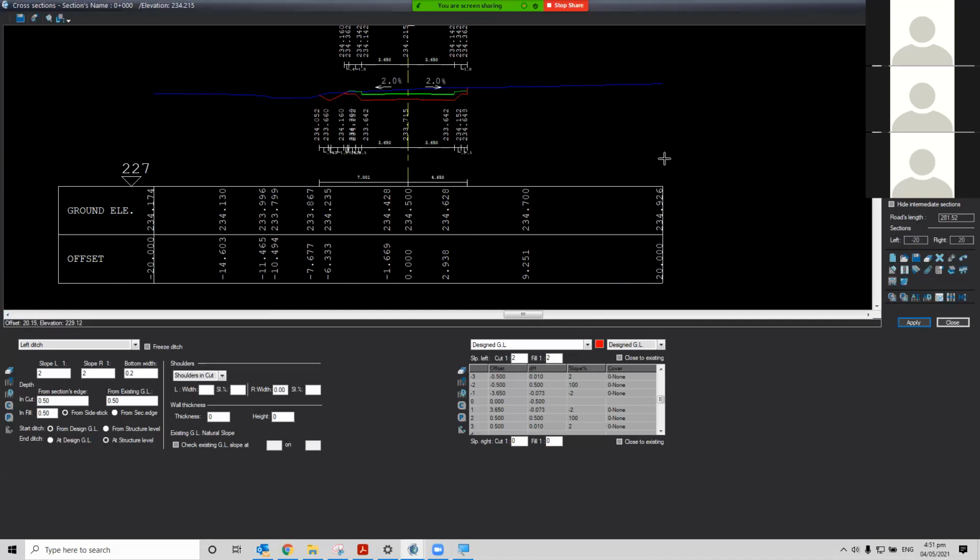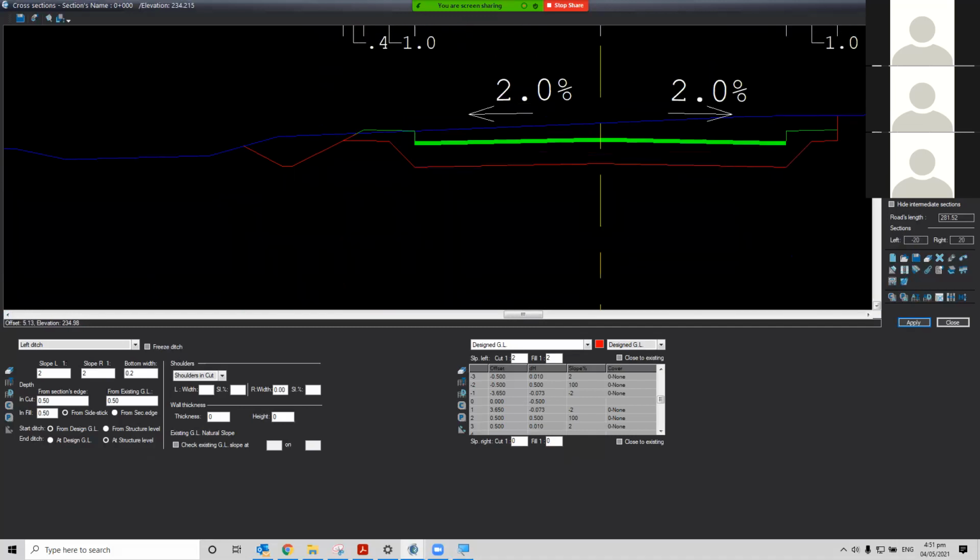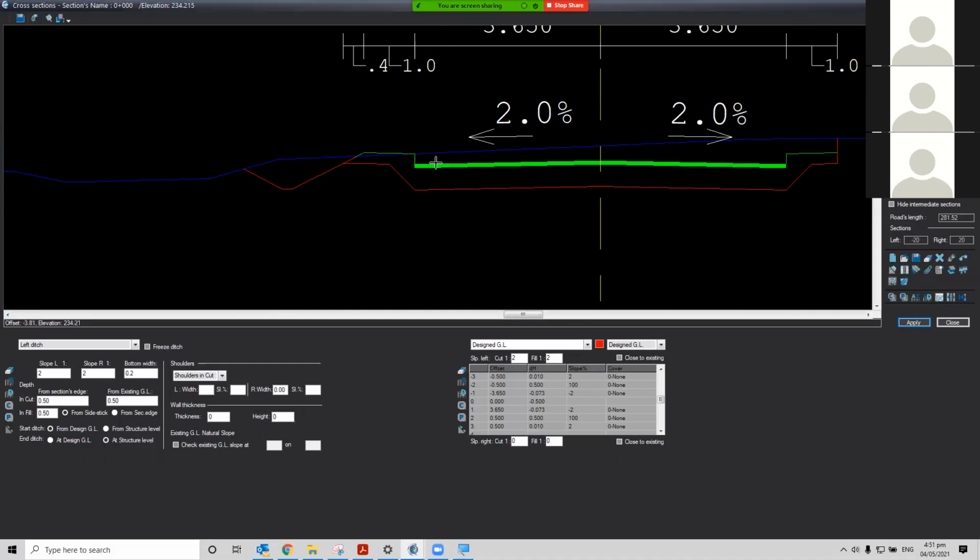By the way, can you zoom to the left? I want to do a small practice with you. See your sidewalk. Your sidewalk has a slight slope going to the road. Yes. Because you entered 2%. Now you might design it like this, but now since you have a ditch, you might want to do the drainage to the direction of the ditch. Okay. You got me?